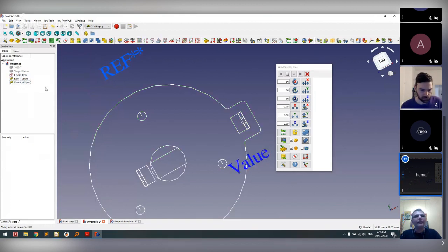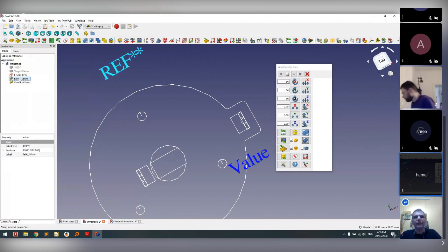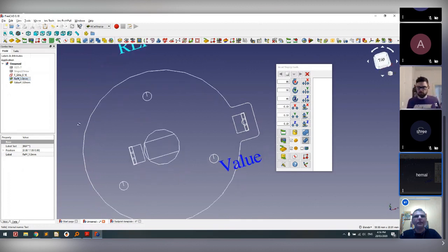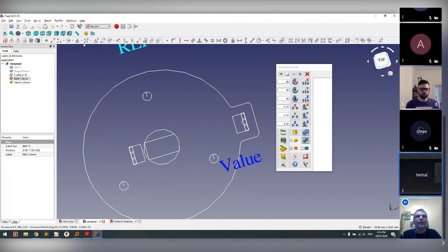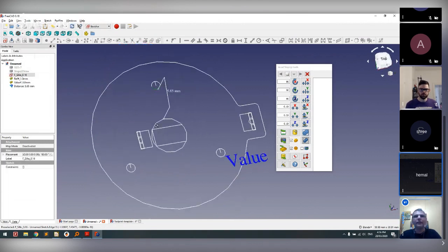The other thing you can do from this 2D drawing is extract some dimensions. If you want to know the bolt circle diameter on which the three posts are located, I'm guessing it should be possible to get a measurement of that. Not sure how we can do it right now, but I'm sure we can figure out a way. You can connect the center points of those three circles as a triangle, and then derive a circle that goes through all of those points.